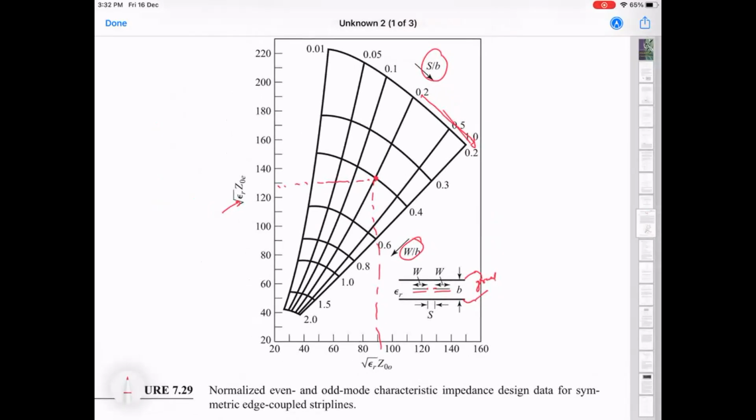I don't have a very convincing answer for why the even mode impedance comes down. But width is also convenient. Huh? C11 itself is convenient. No, width is not. That's width down. No, we are staying on constant width, because I'm on this line. So this line is W equals WB equals 0.2. We're just traveling along this contour, which is fixed width, but changing gap.